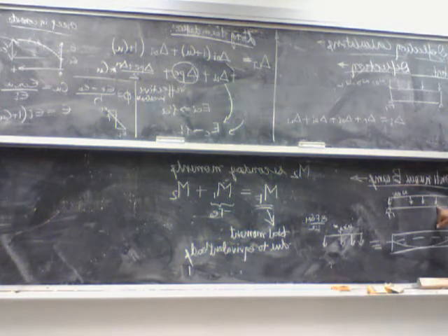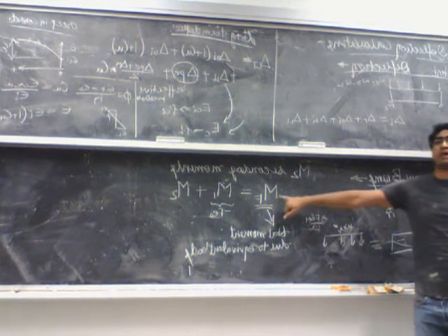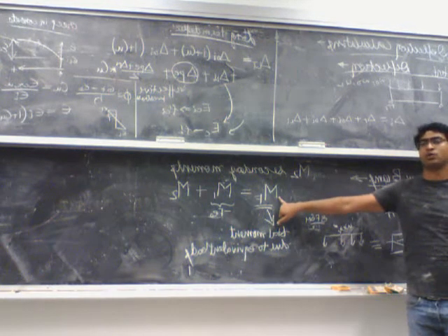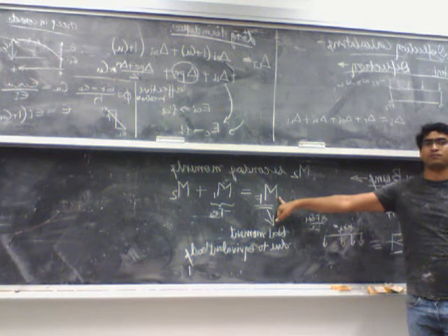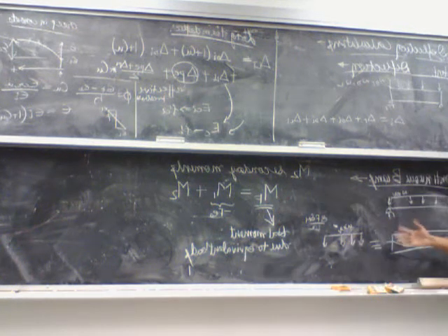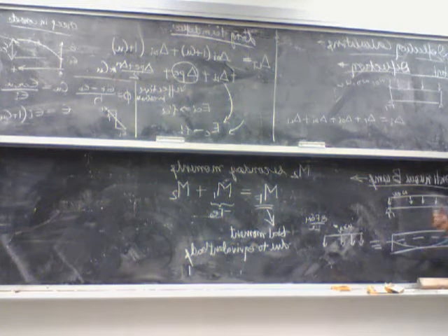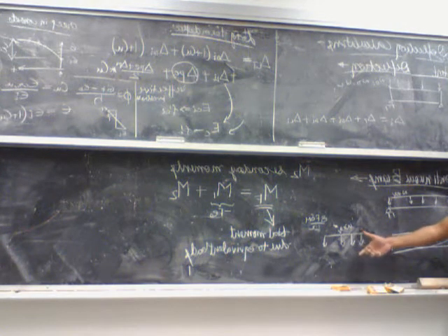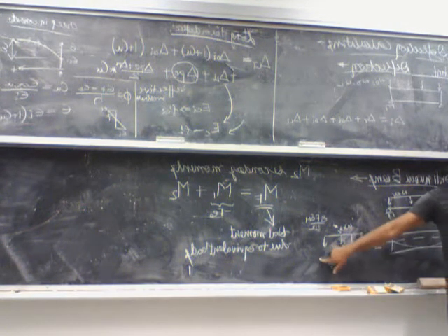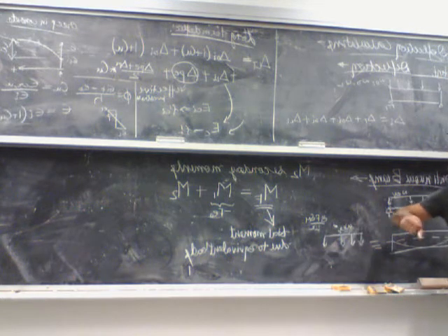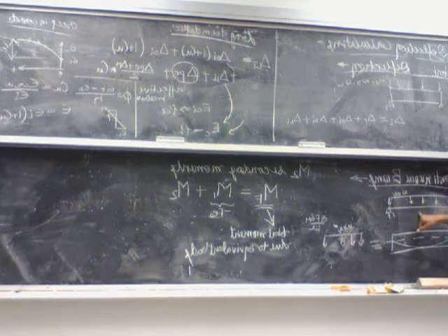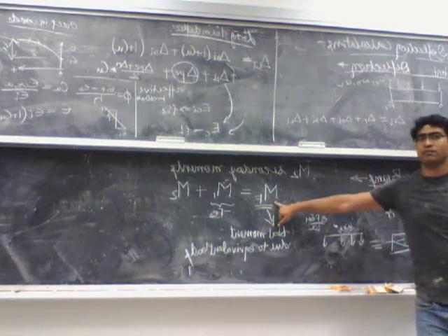And if I draw the bending moment diagram, or the moment diagram for this case, it actually gives me my MF, that is my total moment, due to the prestressing force and the E naught. So what you do is you remove the F, you remove the E naught, replace it by the equivalent loads. For a parabolic tendon, it's actually a distributed load, which is given by this formula. You apply that equivalent load on your beam, analyze it, and that gives you your total moment MF.